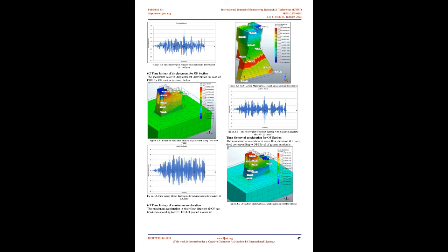The mode superposition method is used in many structural analysis programs and is an effective way to calculate the dynamic response for the linear dynamic analysis of large structures with little computational cost. However, the accuracy of the total response depends on the number of used natural modes, and so, the number of modes used in the calculation need to be selected appropriately.